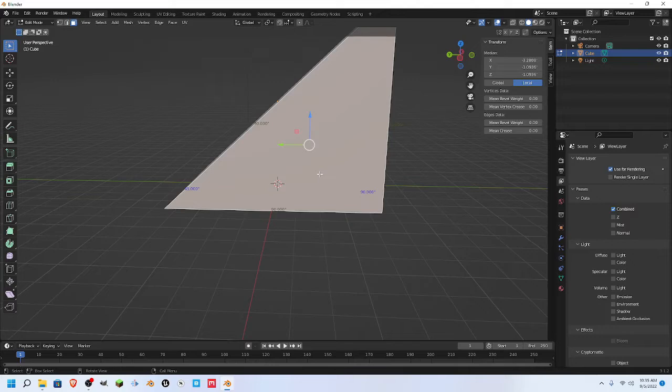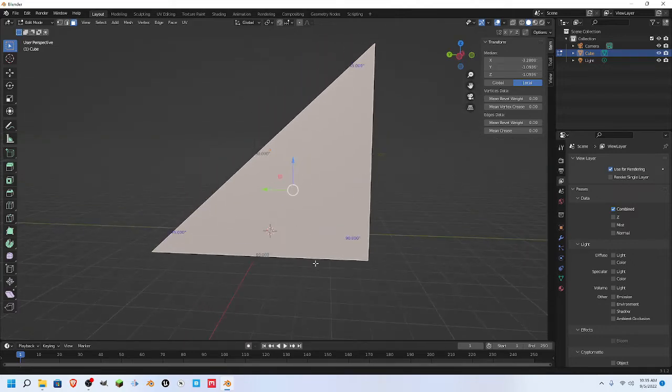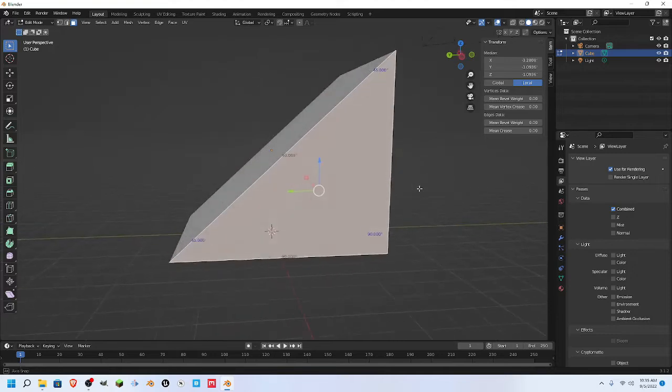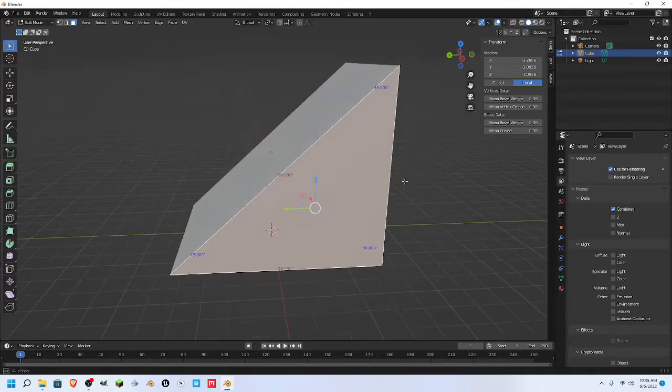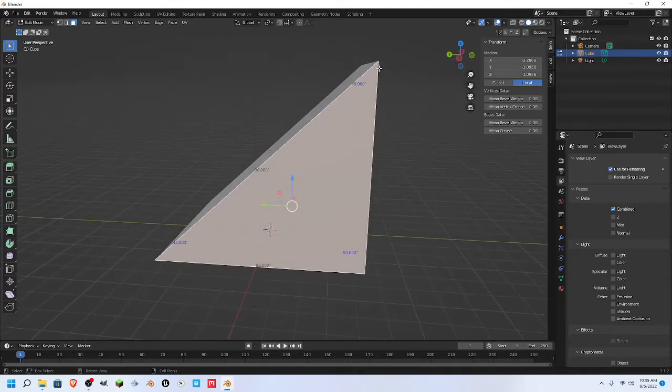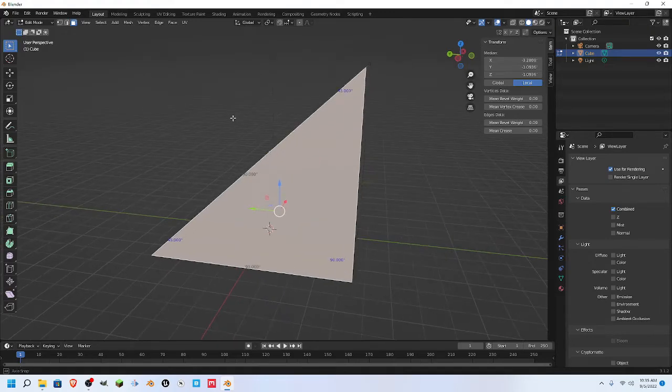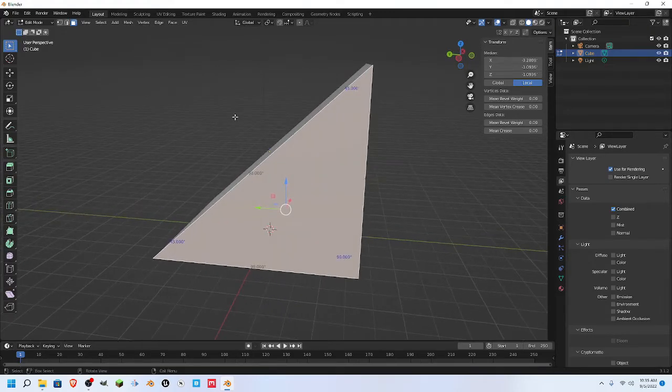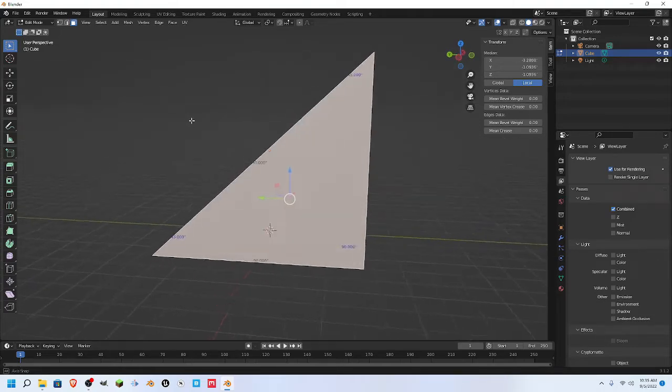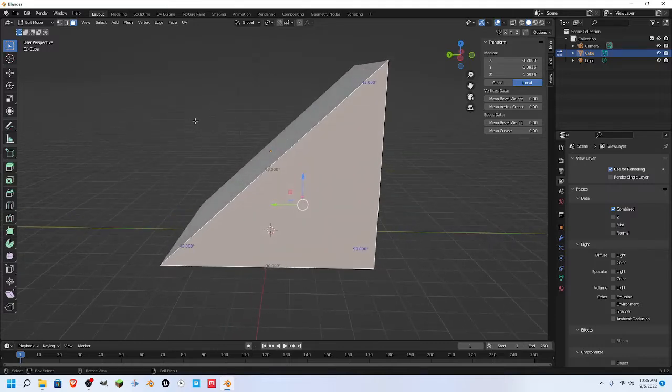We will go to faces and we will grab this face here, and you'll see we have a 90, a 45, a 45. A 45 is a 12 on 12 fall pitch, which means that over the course of 12 inches horizontally, it falls 12 inches vertically. So that is a perfect 45-degree angle. We will be doing a couple of different pitches, and I'll talk about those as we get to them.